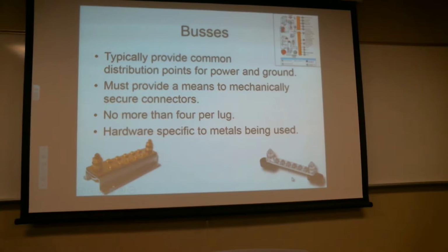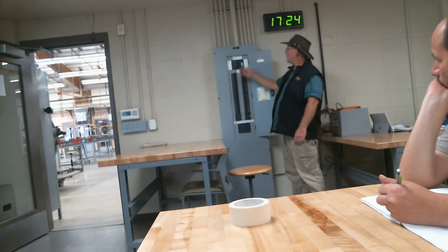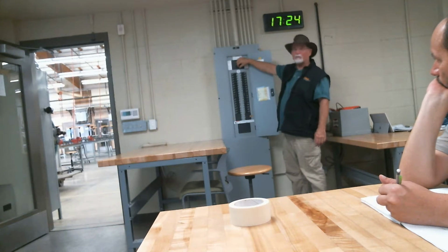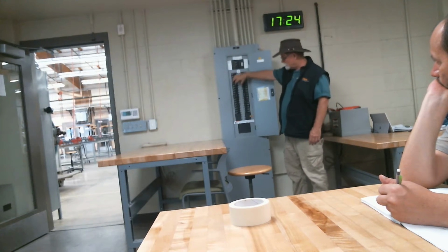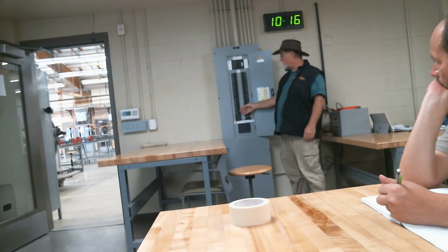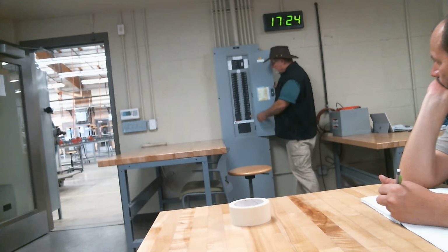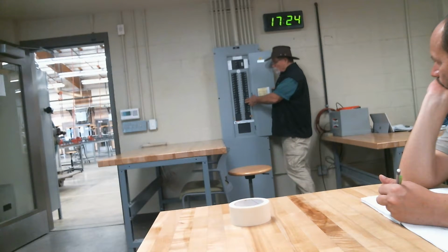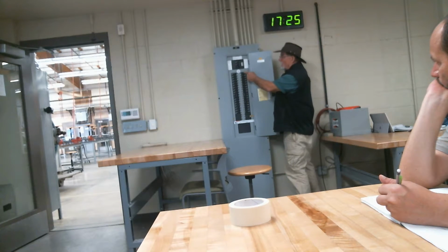In here, there are big fat wires that come into here, and then there are these big metal plates that come down either side. There's three of them. So big fat wires come into here to the three circuit breakers. They then attach to these three big metal bars that come down through here. Those are buses. Then each one of these clips onto each one of those metal bars, depending on whether or not they're ganged. These will clip onto two different metal bars. So each hole is a different metal bar. That'll be bar A, bar B, bar C.